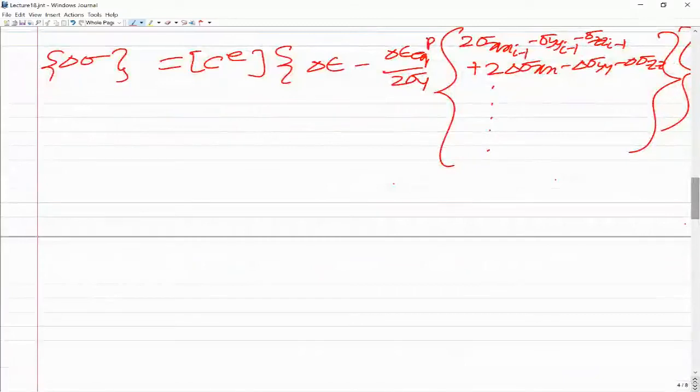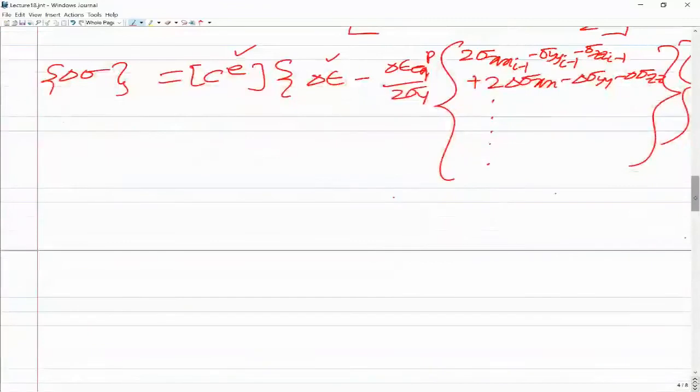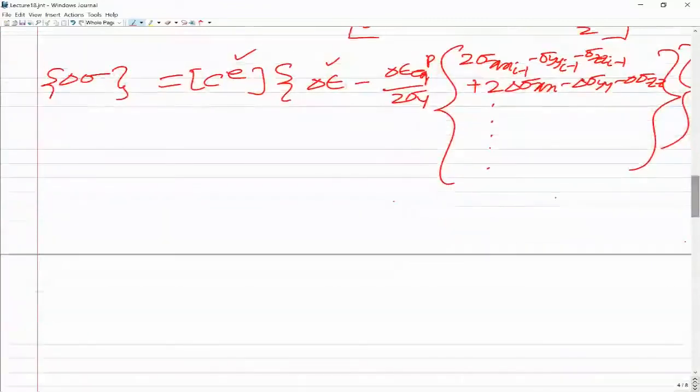So finally you would be able to do one thing. We have this first term, Ce into delta epsilon. C is the elastic matrix, delta epsilon is the total strain increment in the ith iteration. If we take this multiplication as some tensor s, we can say that it is the predictor, where we assume that this step is an elastic step.